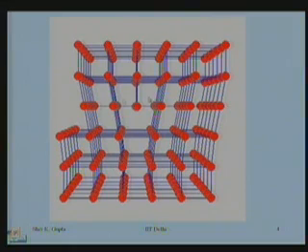Notice here in this space I have more planes, and in this space I have fewer planes. Obviously that has to be adjusted. You squeeze the top part only. It is also relative. You can say that you have pushed the top to the right, or you can say that you have pulled the bottom to the left. So there is going to be an extension here, because after all the space is the same in which all these 6 planes are arranged. Therefore there is a compression in this region, and there is tension in this region.